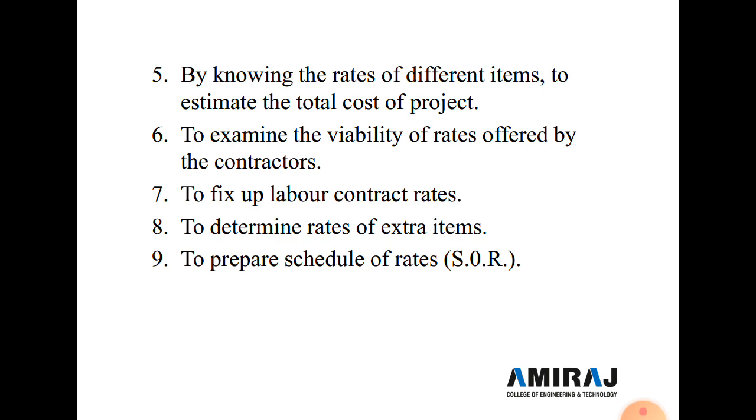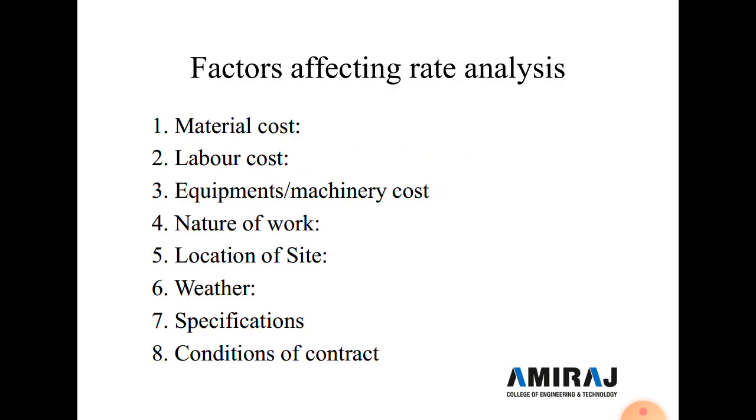Now in the next slide we discuss some of the factors affecting the rate analysis. The first factor is material cost. Material cost is an important factor affecting the rate analysis. Materials like cement, sand, steel, aggregate, etc. vary in cost from place to place.